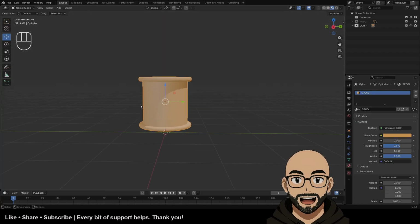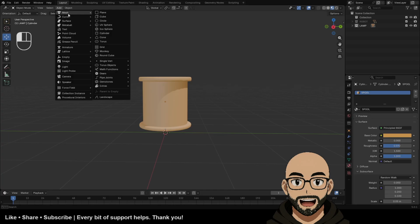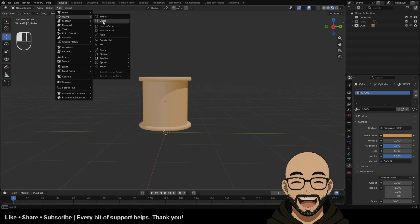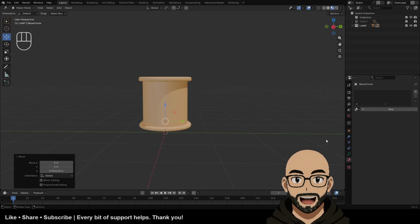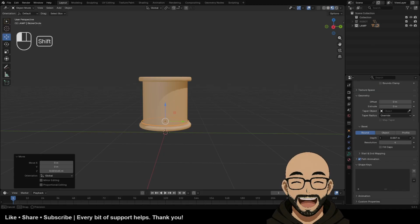And what I want is wire to wrap around this, right? So I want some wires. What we're going to actually do is we're going to use a torus. I'm going to mesh. Actually, let's use a circle. I'm going to use a curved circle. So then we can play around with the thickness a lot easier. I'm going to go to the properties of the circle here and change that bevel.